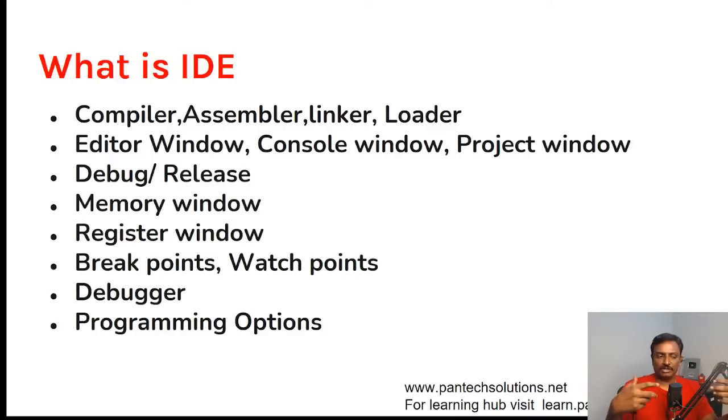And the debugger is for debugging, and programming options are to program the microcontroller. Some microcontrollers support ICSP, some you have to program through JTAG, and some support OTA, like over-the-air programming or in-application programming. So it depends upon the microcontroller. Okay, is IDE clear? So IDE is clear.